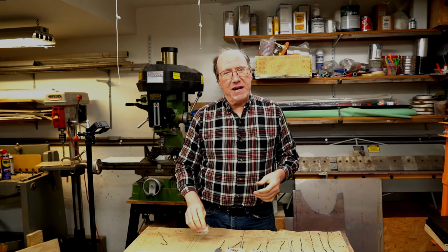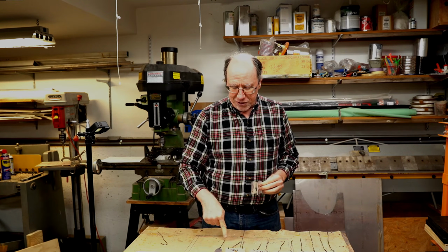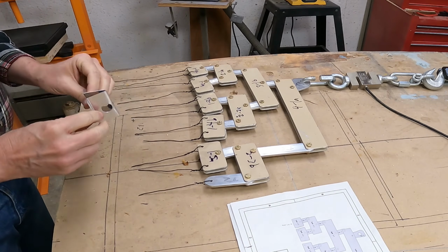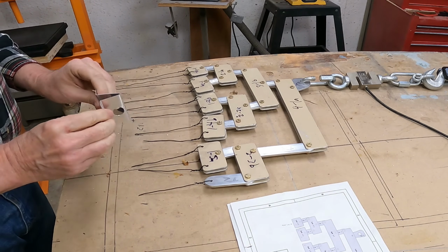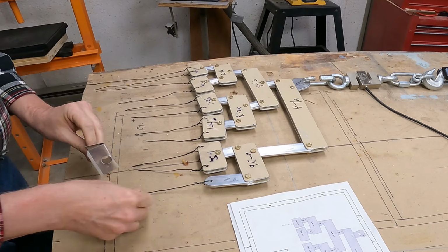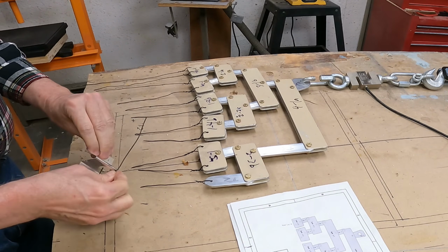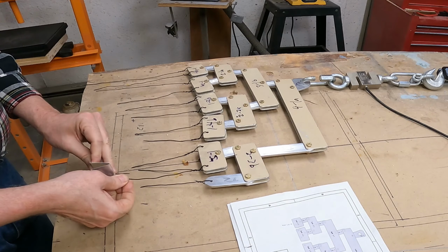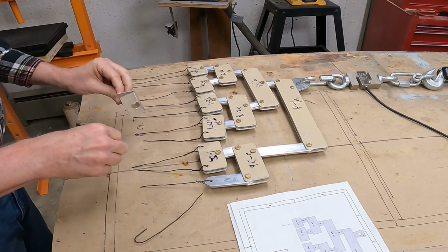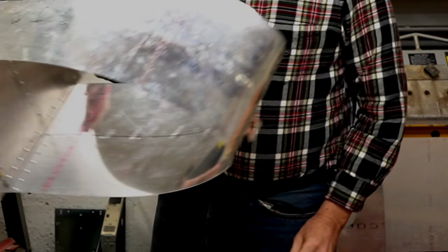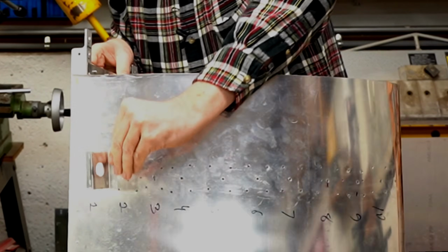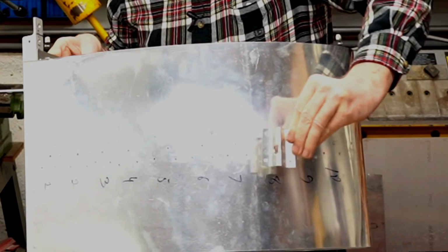So I mentioned before a fixture that I was going to tie these wires to, these load wires. This is what I'm going to rivet to the skin of my rib fixture. We'll just put a hook down here in this wire, bring it around, and probably do a little twist on it to hold it. And we'll do that at each rivet location. So basically, this form will have a bunch of these riveted along here to apply a load at each rivet.